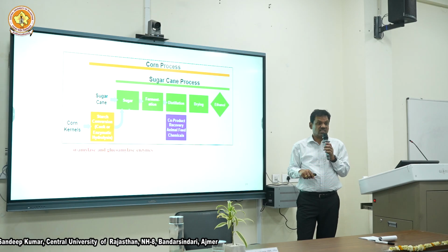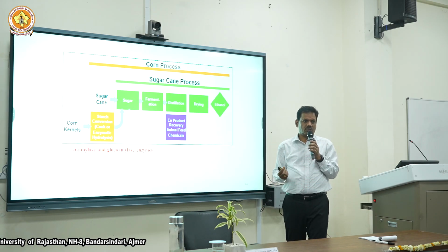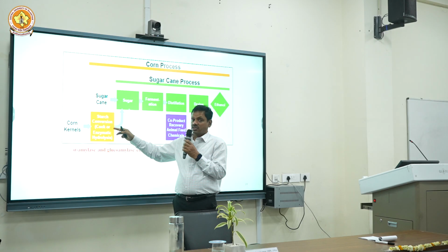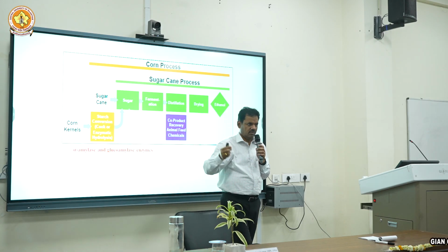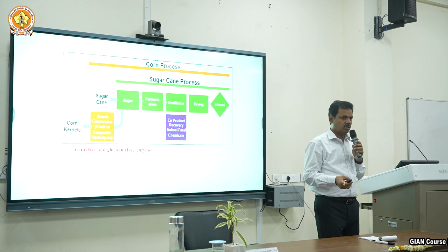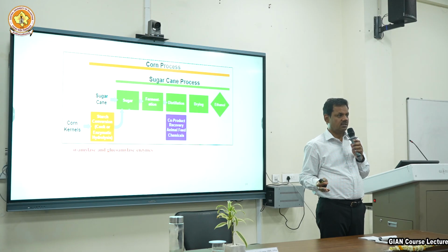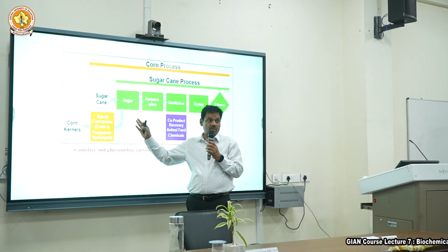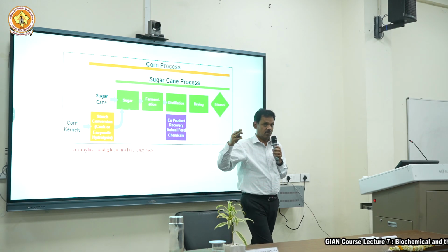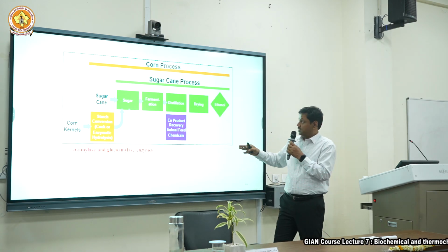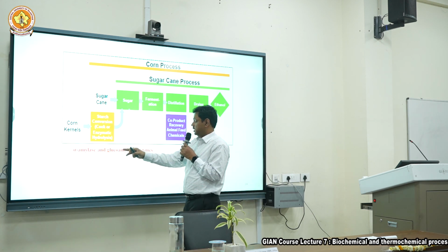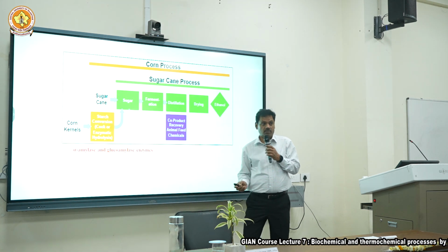Let's say you have a starch, corn or something. If you have a starch, then you need to cook it, make it softer, bring it into solution, basically hydrolyze. This is again commercially known, so this is easy to do, but you added one step, cooking of the starch. And then the remaining process remains the same. The enzymes are alpha amylase and glucoamylase. Okay.